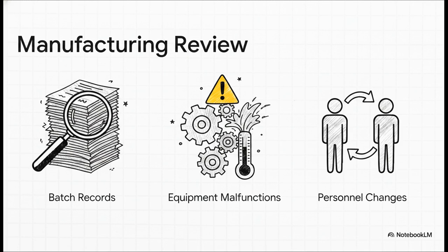Here, we're scouring the batch's birth for hiccups. We're looking for any tiny deviation in how the product was actually made. We scrutinize the batch records, we hunt for equipment malfunctions, like did it heat up or suddenly spike for 10 minutes, and we profile any personnel changes, like a shift change or maybe a brand new operator stepping onto the line.